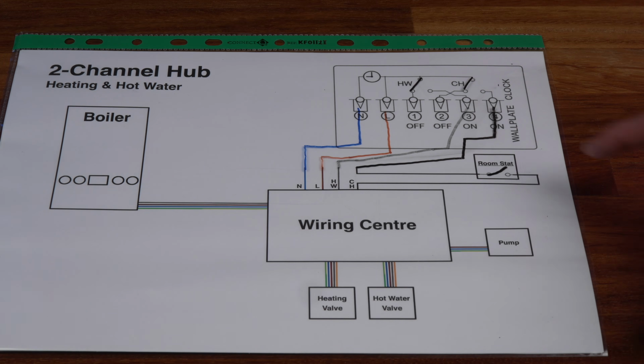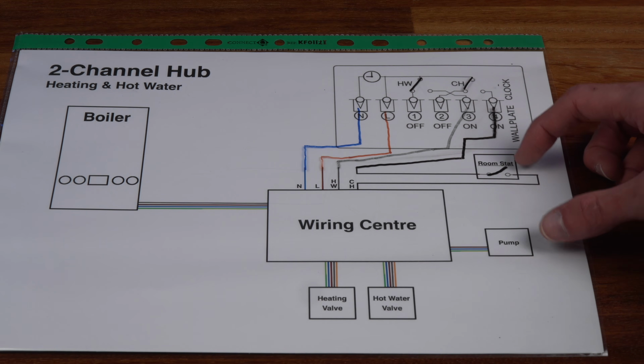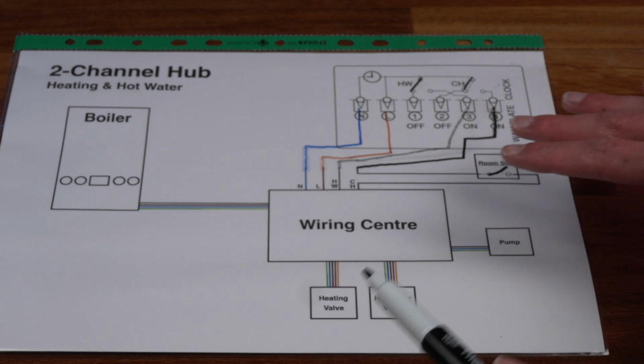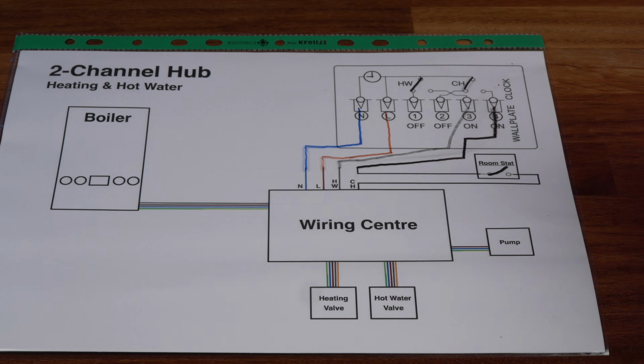Alternatively, you could just leave this thermostat always set to its maximum temperature and hope no one ever touches it. Or if you just want a quick approach to bridge it out, take the front off the thermostat, link the 2 wires together inside it, put the lid back on, and it'll be completely linked out, work normally, and you've just got a thermostat on the wall that doesn't do anything.